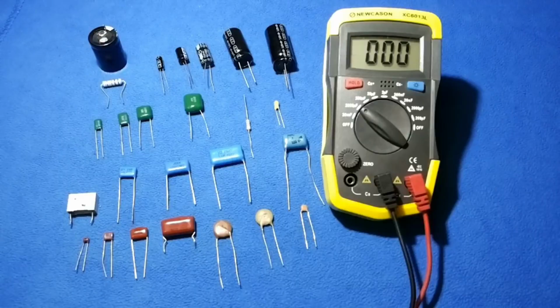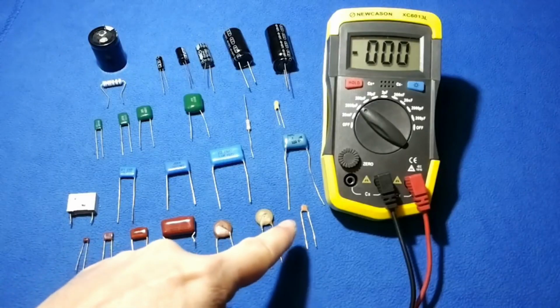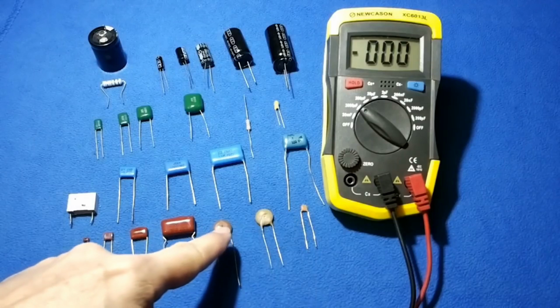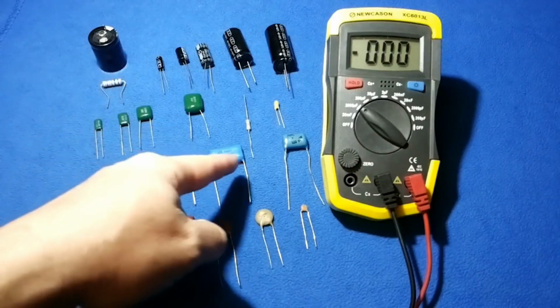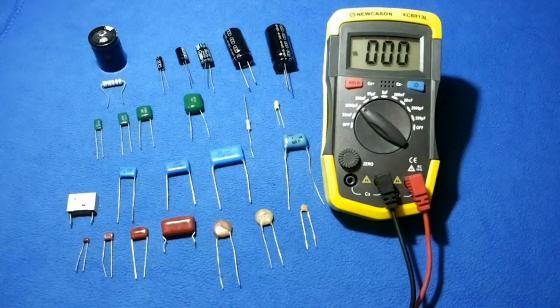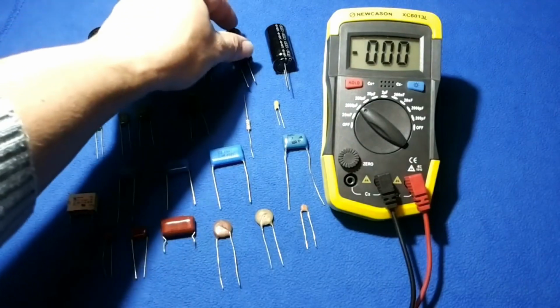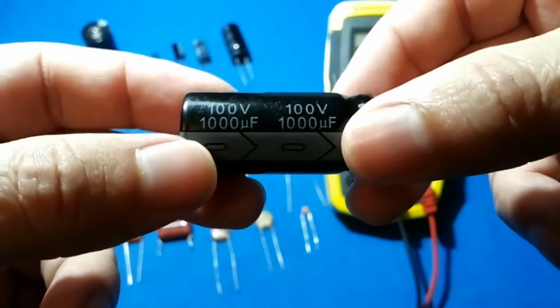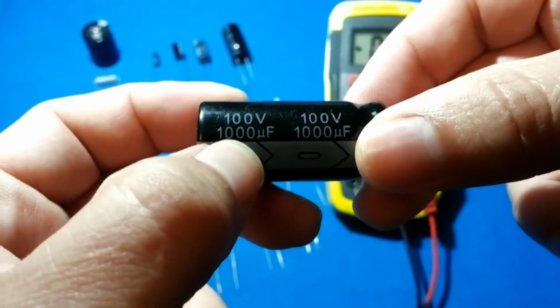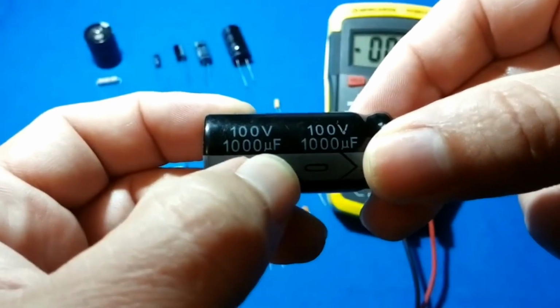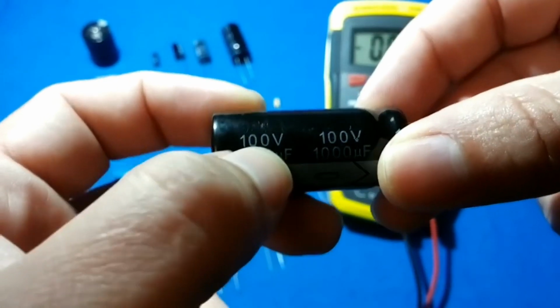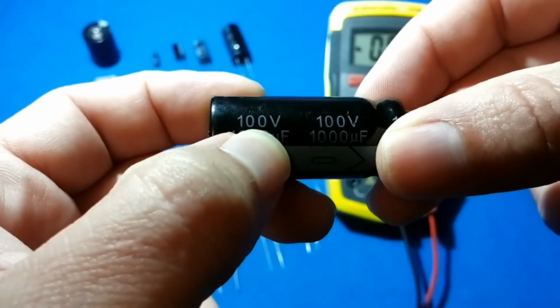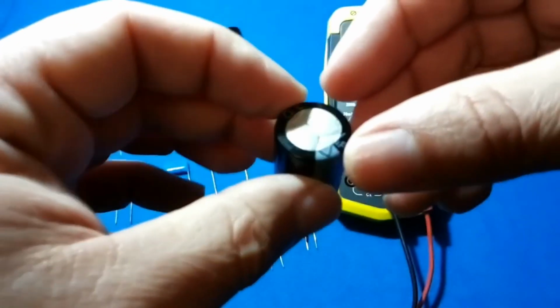There are various types of capacitors, such as ceramic and electrolytic, each exhibiting unique characteristics and capacitance levels. Grasping these distinctions is essential for their appropriate application. When replacing a capacitor, it is imperative to match the capacitance value accurately while also considering the voltage rating. Additionally, the temperature rating plays a critical role in ensuring the reliability of the capacitor.